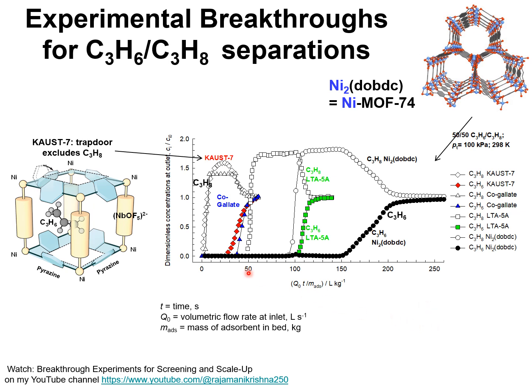In my presentation today, I examine the variety of factors that determine the extent of deviations of the phenomenon called a rollup that is experienced for propane, the less strongly adsorbed component, and I show that the extent of rollup depends on a variety of factors that include the composition of the feed mixture, the diffusional influences within the pores of the metal organic framework or zeolite, the contact time between the crystals of metal organic framework or zeolite and the gas phase in the fixed bed adsorber.